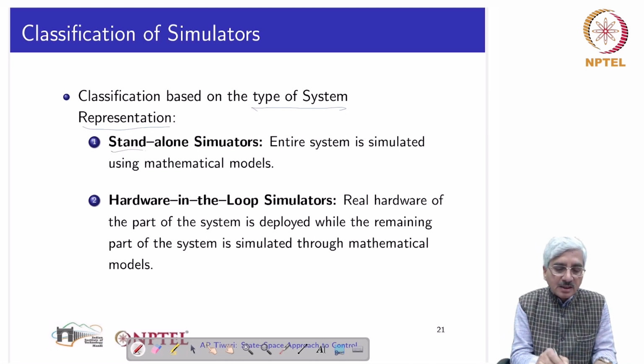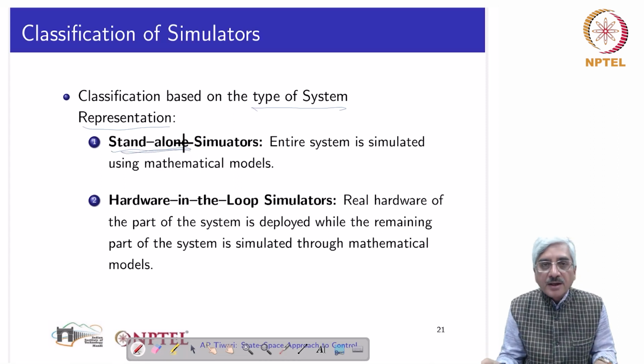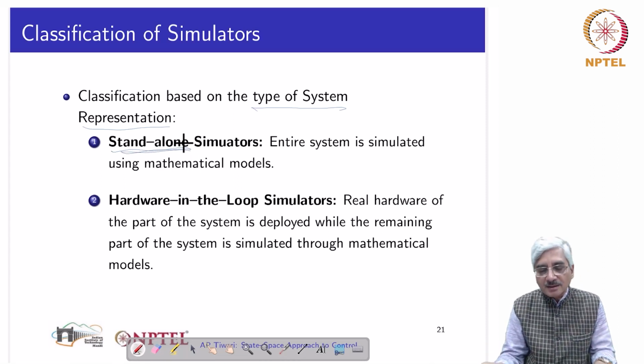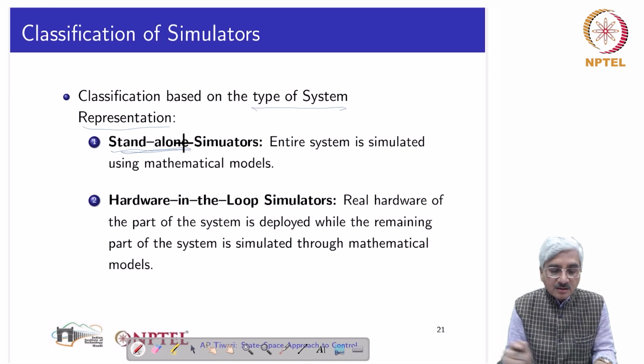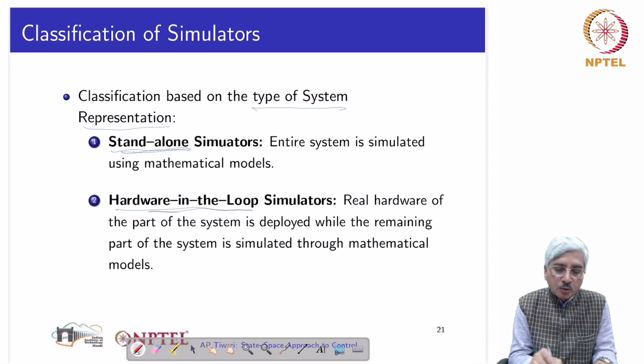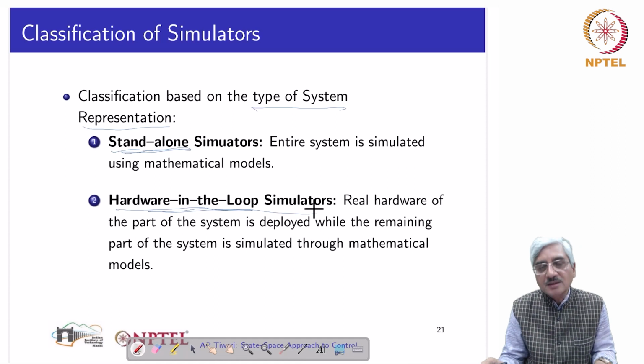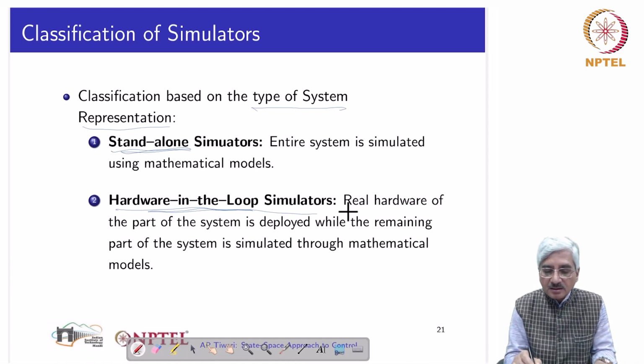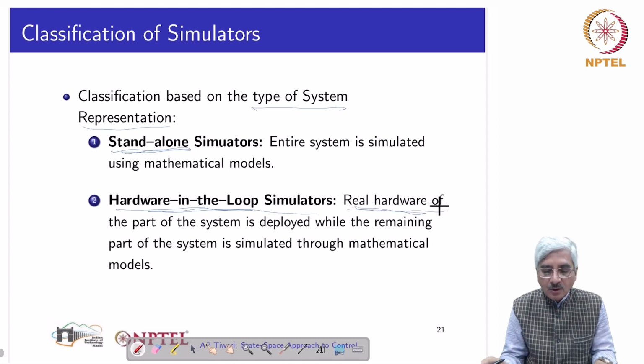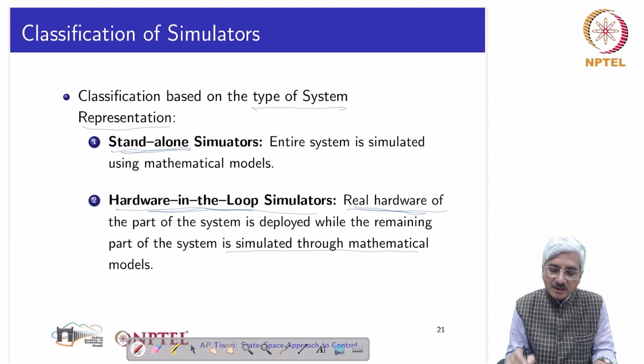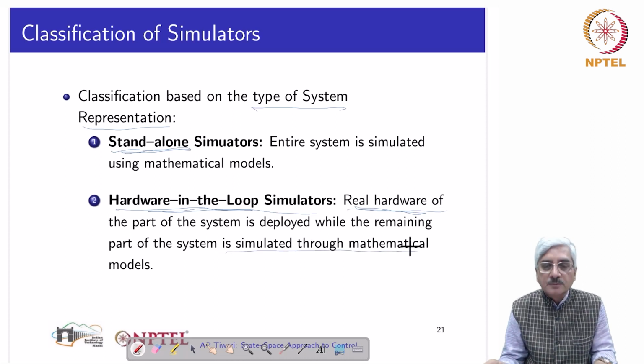So one can have standalone simulators. Entire system is simulated using mathematical models in one simulator. Other possibility is hardware in loop simulators. In this, some part of the system exists in the real hardware, which is interfaced to the remaining part that is simulated through mathematical models.